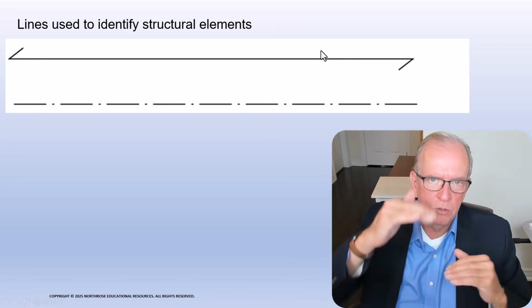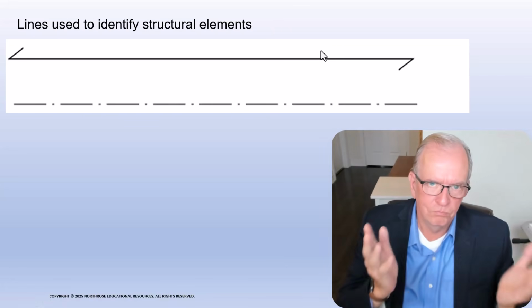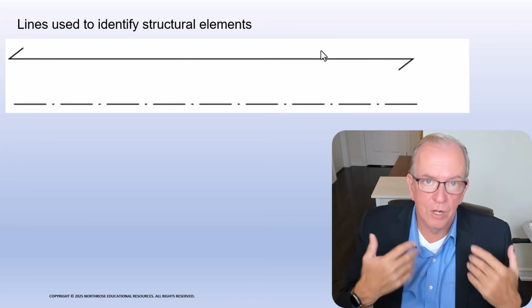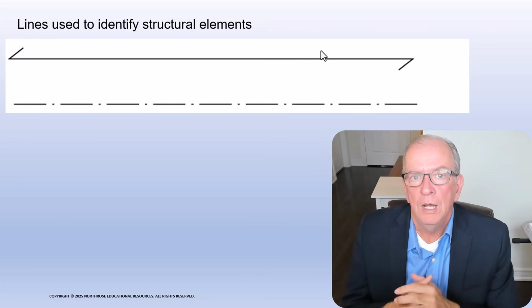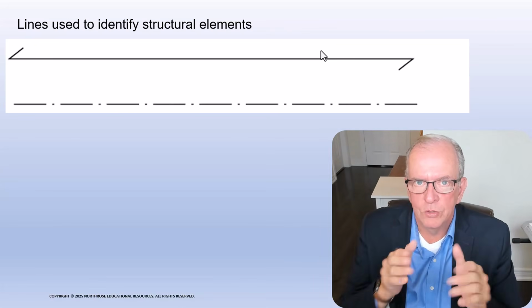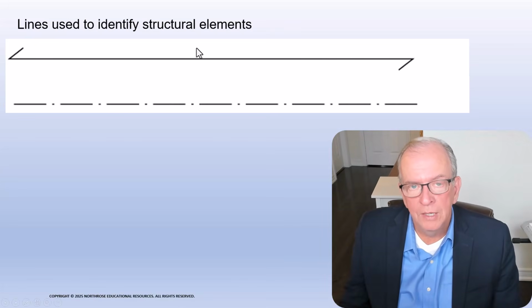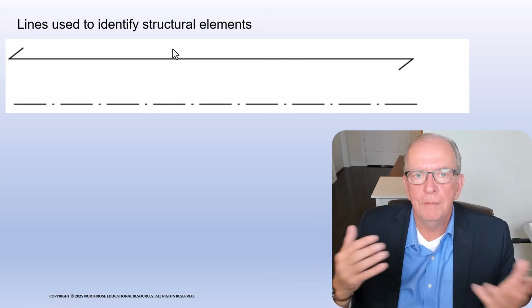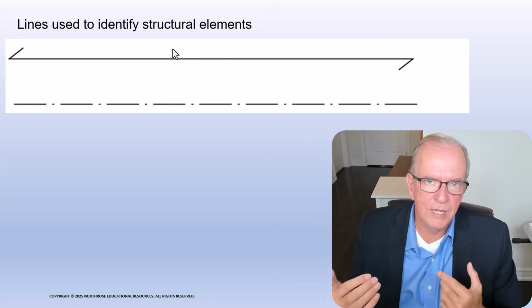That means you're putting 2 by 8 inch joists, for whatever species of wood in your area. Ours is spruce pine fir. And it's going to go in that direction. If it's in metric, it might say 38 by 235. 38 by 235, that would be like a 2 by 10, right?